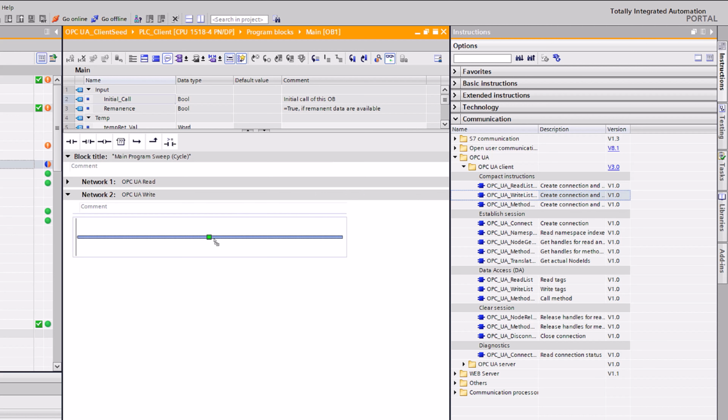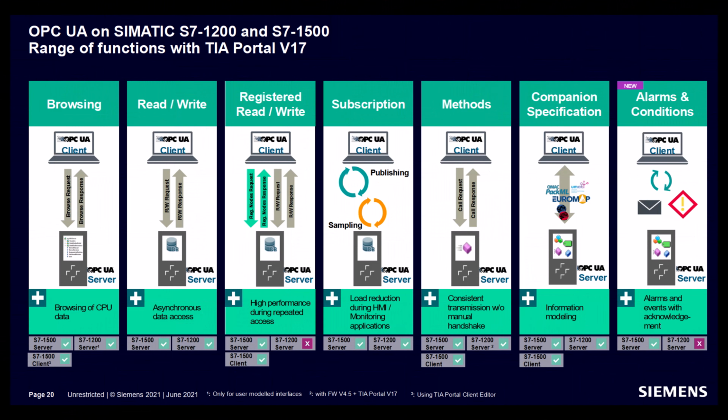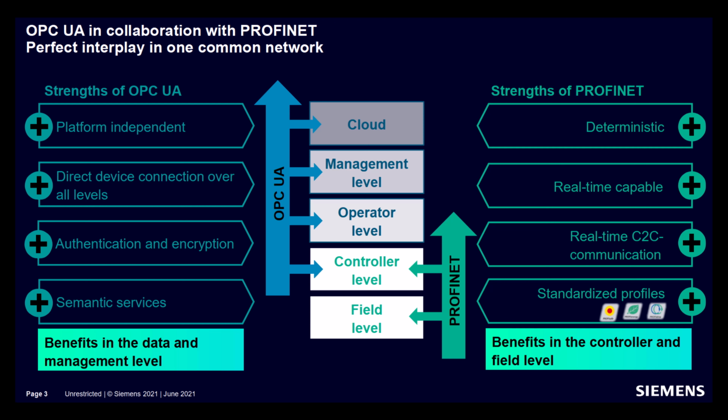Siemens offers the OPC UA communication protocol for standardized communication of an S7 control system across all platforms and manufacturers. As of firmware version 2.5 and TIA Portal v15, the Simatic S7-1500 control system can now offer OPC UA methods to clients via its integrated OPC UA server. This means that you can not only read and write OPC UA variables of the control system, but you can also start complex functional sequences via OPC UA. This enables almost complete machine-to-machine communication through the use of OPC UA, which can be used for plant networking or plant control from an ERP/MES level.